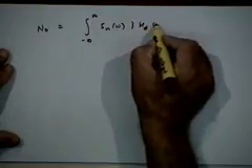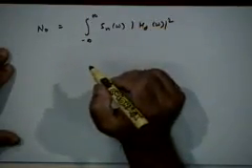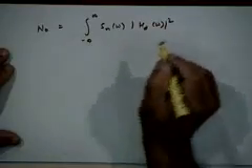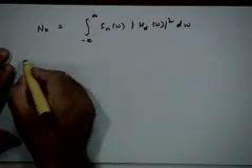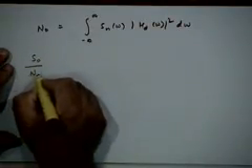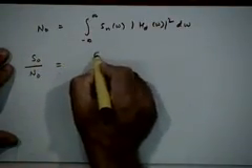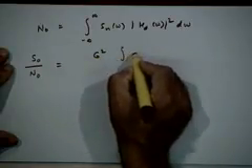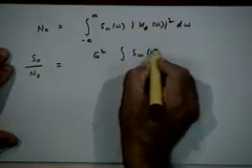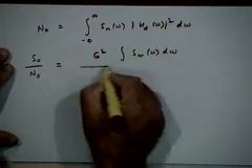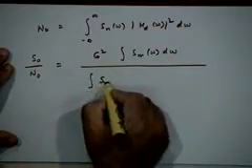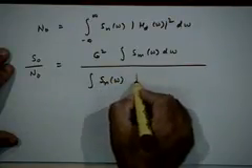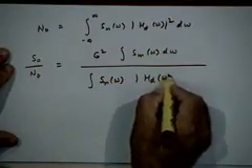H_D(omega), because noise will only go through the receiver transfer function, H_D(omega), right. So therefore the expression for S_0 by N_0 is G squared integral of S_m(omega) upon integral of S_n(omega) into mod H_D(omega) squared.